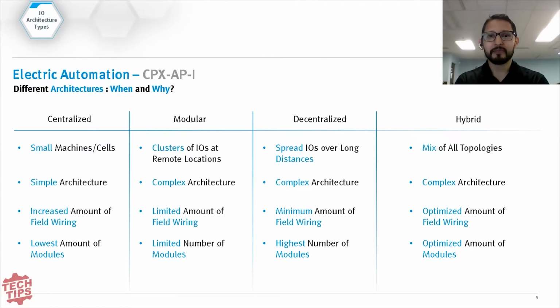Compact machine, we're seeing people get away from the centralized and going to on machine, just because of the cost of running everything back versus a field bus of some type. Right. It's still landing everything on a terminal block and then wiring in those quick disconnect cables along with on machine type devices can save maybe not the pure hardware bill of materials, but the overall construction and wiring. It saves a ton on the cost of putting the system together.